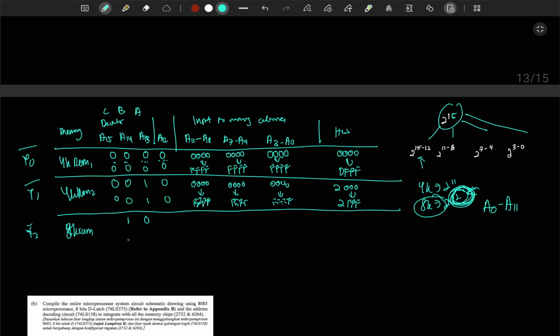Now this is the 4 for our hex. I want you guys to see these 3 for our decoder. Do not be confused. These 3 are for our decoder, this 4 is for our hex. Now if we make it as such, we know that this is equivalent to 4000. So our starting address is now 4000, and as said, 8K is equivalent to 1FFF.